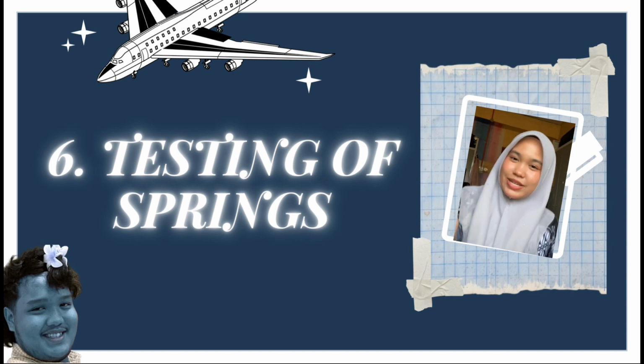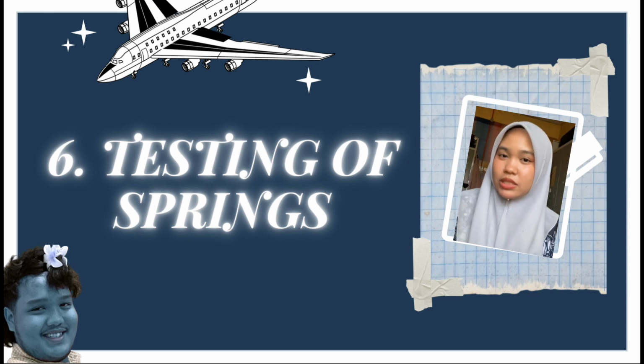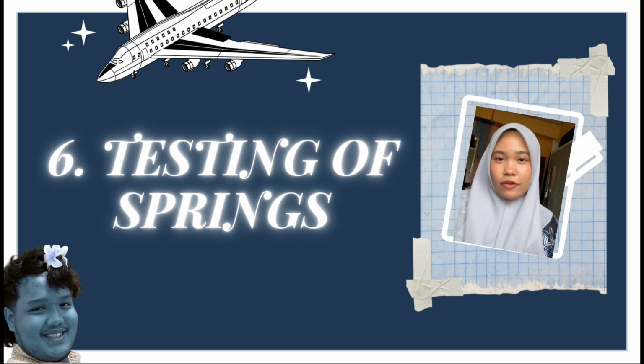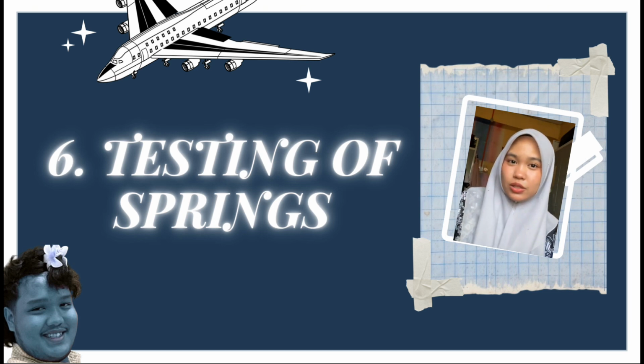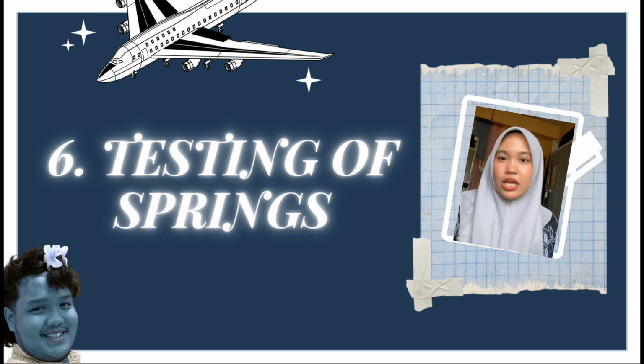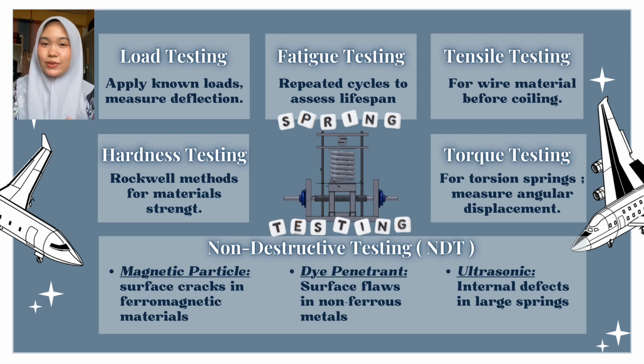So what is spring testing? Spring testing is a critical process that ensures the performance, reliability, and safety of spring components used across industries. Let's take a closer look at the different testing methods used to evaluate spring quality. First is load testing. Load testing involves applying known loads to the spring and measuring its deflection. This process helps determine the spring stiffness, load capacity, and overall compliance with design specifications.